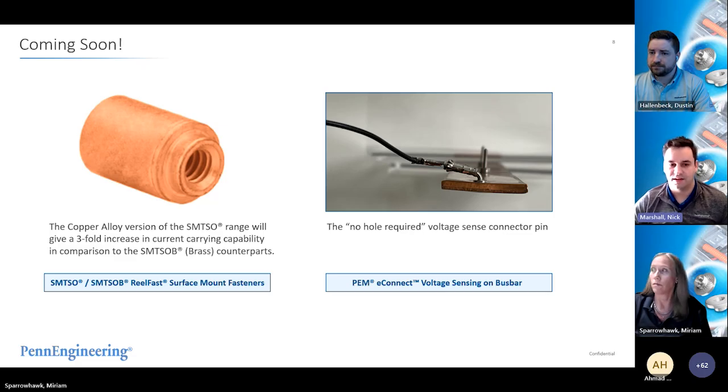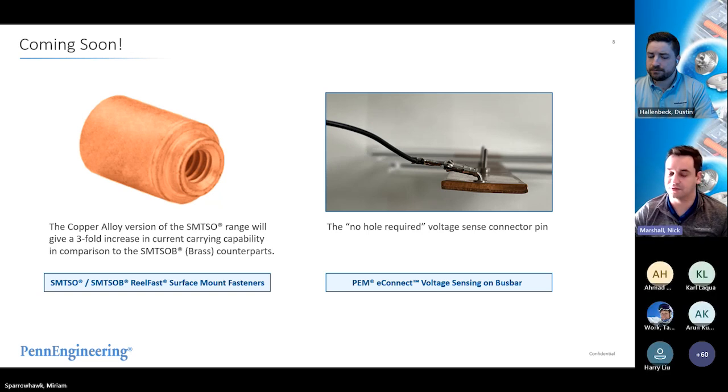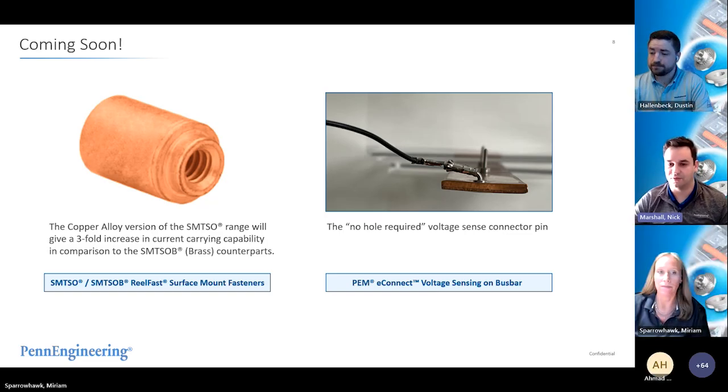We initially started with busbar to busbar connections, where we were trying to make those simple joints from one conductor to the other. But we're seeing increasingly that customers need to join those bus bars or those other systems to additional components like PCBs or wiring harnesses, whatever it may be. And so they need a solution similar to what we've developed for bus bars for those applications. And that's where the SMT would come in, is when you're trying to create a joint or a terminal that can apply that current to some of these larger electronic circuits that we see, this is an option for that.